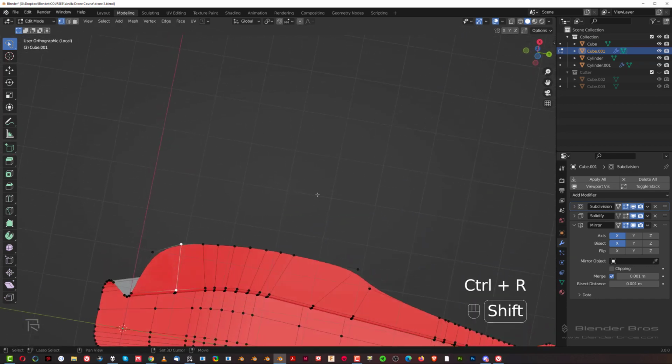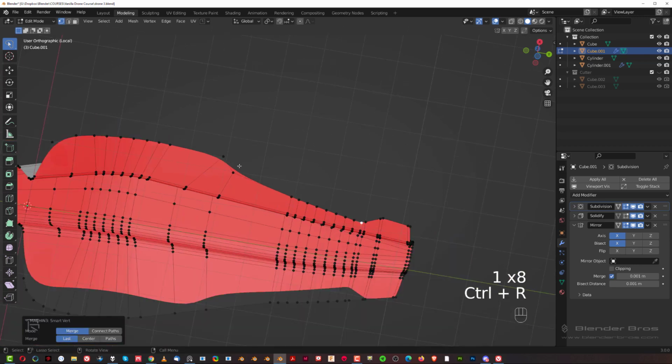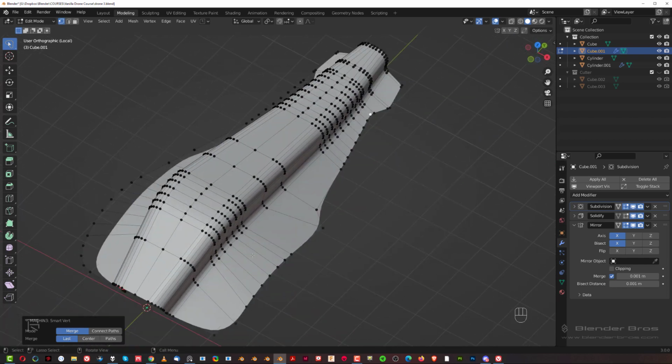It still doesn't go through, which means we still have some n-gons. So we need to check that out. There's an n-gon in here, there's an n-gon in here, and here, and here. This is after booleans, guys, okay? So you need to, you know, fix these. And now I think, there you go, the loop goes through, which means all of them are quads.